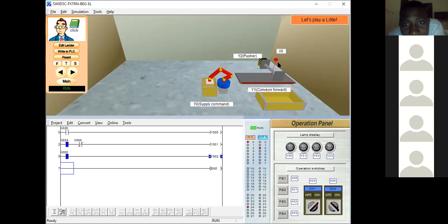Now something needs to reset the pusher back, because the pusher is still sensing. Something needs to reset the sensor, because if you check very well, the sensor here is still sensing this iron. This is a capacitive sensor. It can sense anything here. So we need it to reset whatever is here. Okay, so let's reset first. Then we need to know how to bring this guy back.